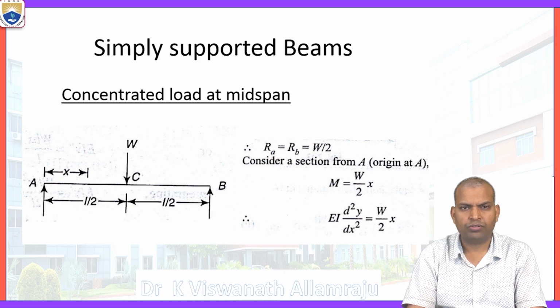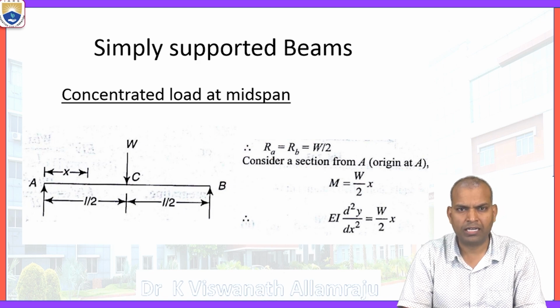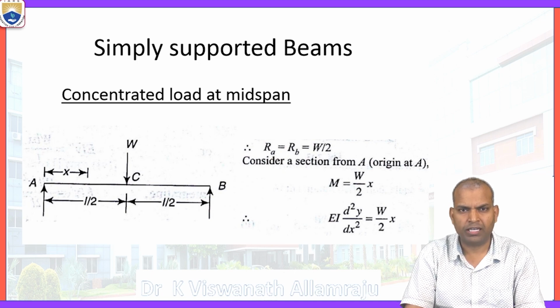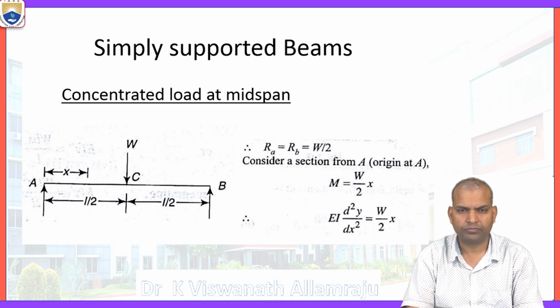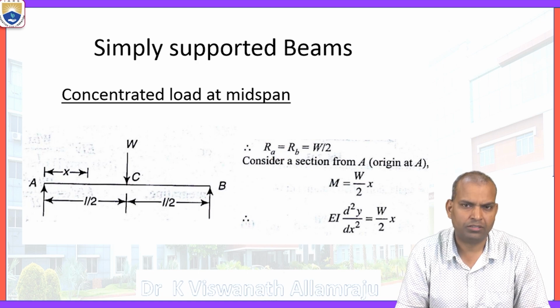Another case is a cantilever beam subjected only to a moment in the clockwise direction at the free end. And finally, a uniformly varying load acting on the cantilever beam throughout the span of the beam. So those are the case studies. We derived the slope and deflections at the fixed support and at the free end by using the double integration method.